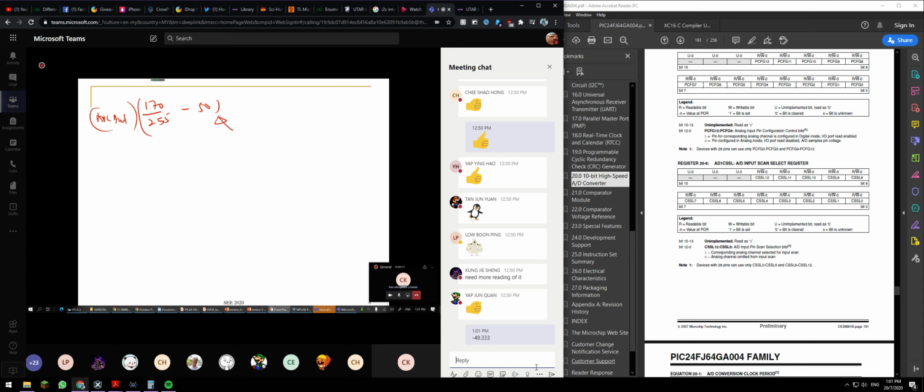But you must remember that most microcontrollers do not come with a math processor. When you perform this mathematical calculation, let's say in C programming, you consume a lot of your processing power and burden your microcontroller. So the rule of thumb is you build your own lookup table. This means you need to build a lookup table from 00000000 until 11111111.